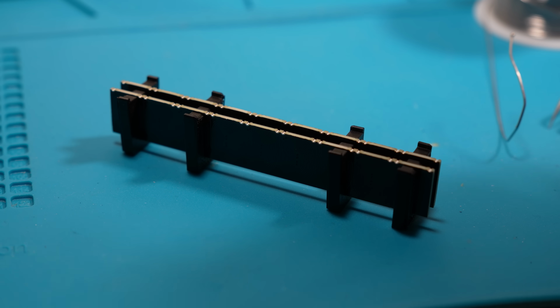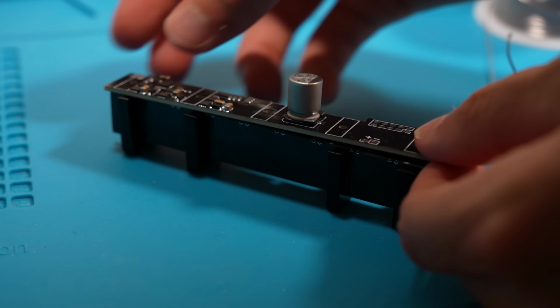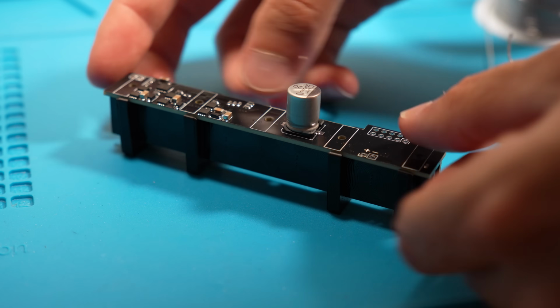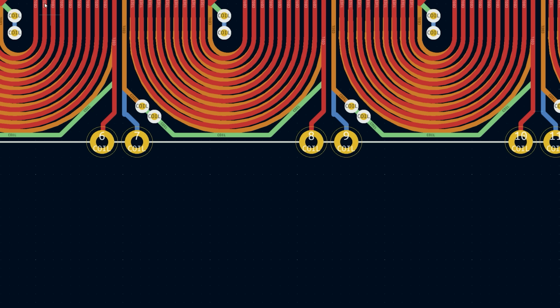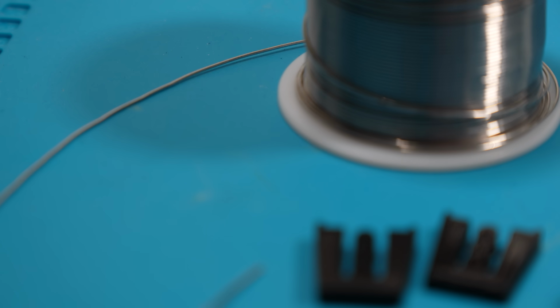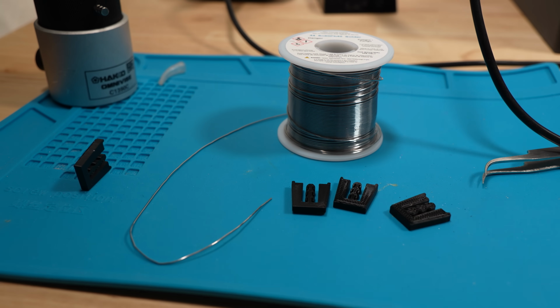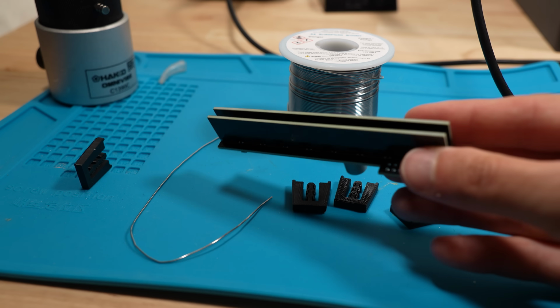Now to attach the coils. I wanted to keep a very clean form factor here, so I tried something new, edge soldering, which really just involves putting holes at the edge of the board and crossing your fingers. And my implementation was an absolute nightmare to solder, but it kinda works, so it's fine.